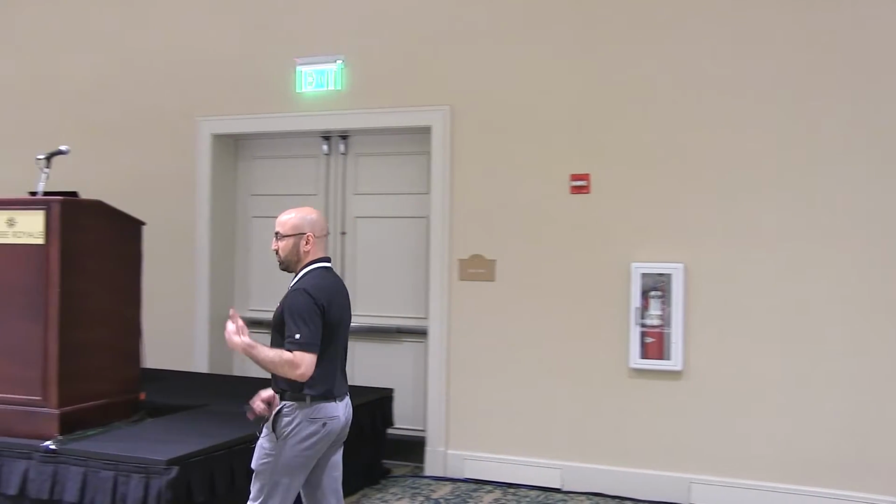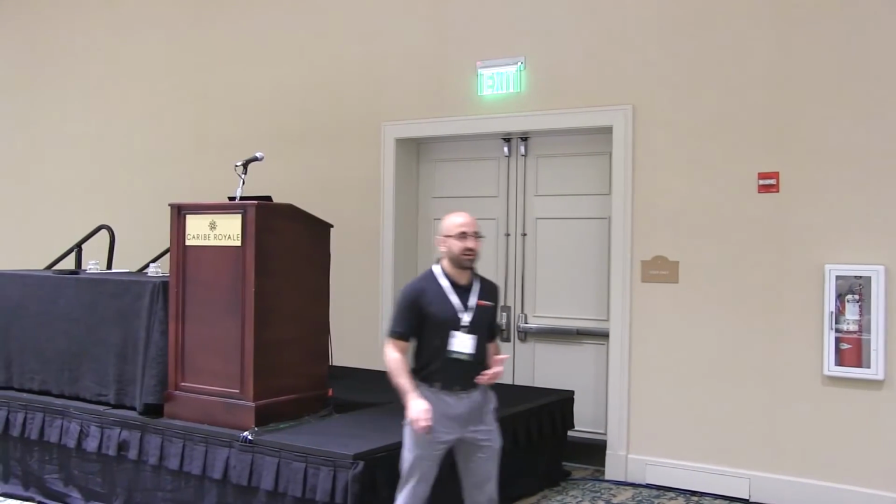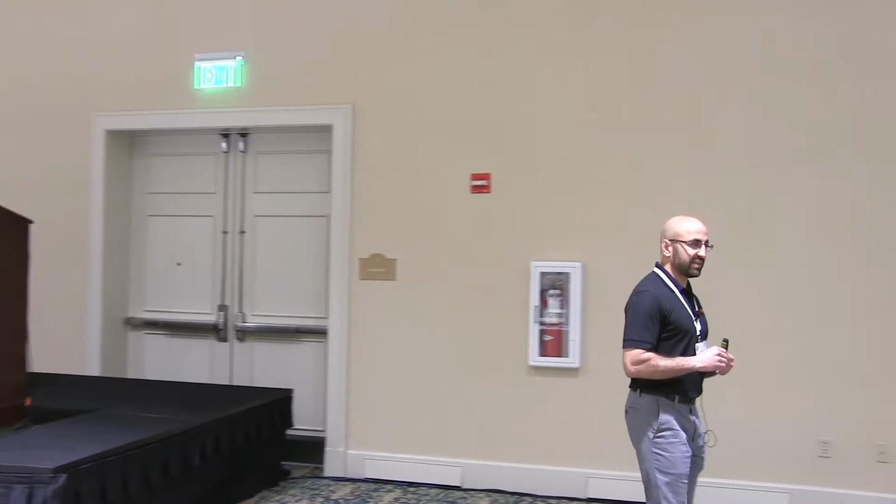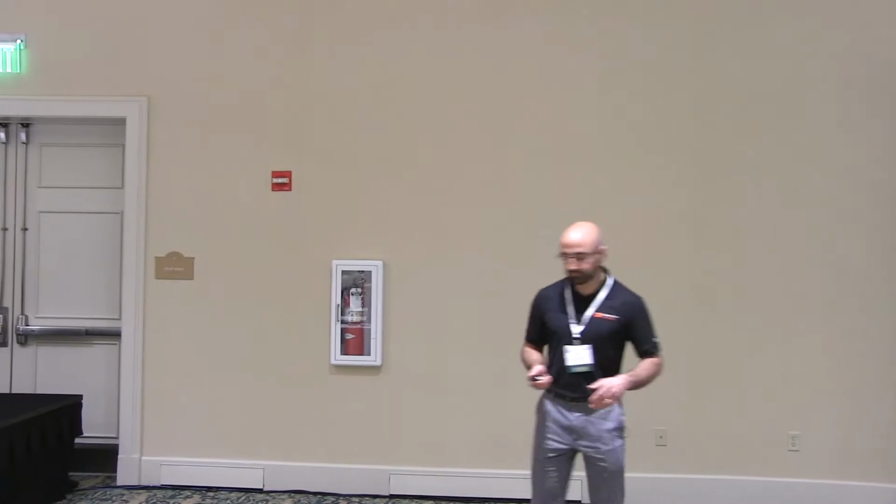Okay, there was a couple here. You want to go next? How do you connect and communicate to a BA system? Repeat the question. How do we connect and communicate to a building automation system? That's a great question. There's a number of ways because we have to be flexible in this industry, right? There's commercial buildings, cookie cutter is not part of our vocabulary, right? So we can either pull the trend log data from a SQL server or any kind of historian. That's one option if the trend log is already set up.